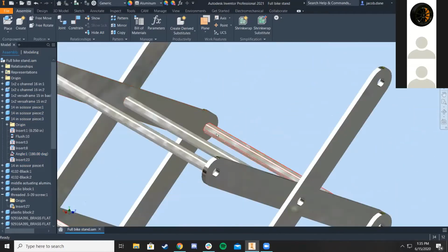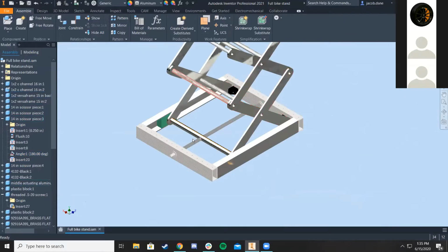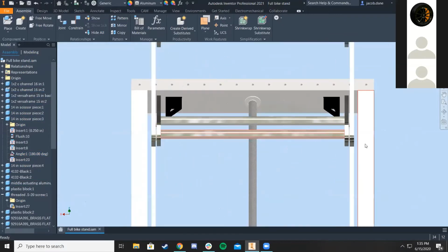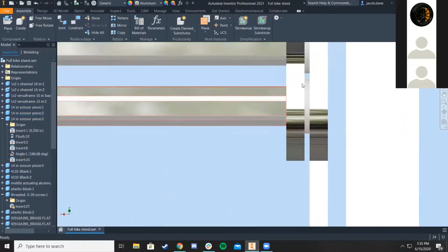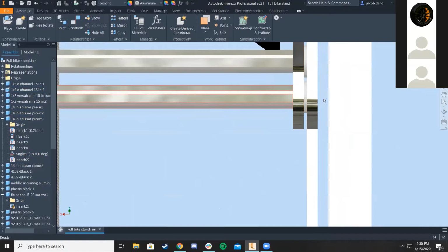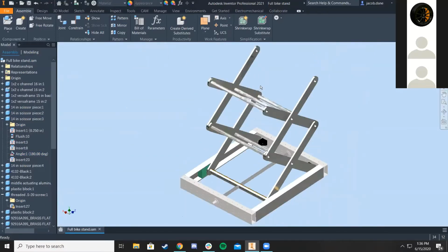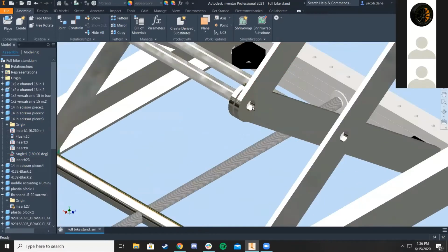And there's also washers. If you click on the back view, there's little tiny washers in there. Those are also in between. You probably just constrain it when you're constraining the scissor pieces, onto each of the edges, and it'll put it nicely. And the hole of the washer fits nicely with this hole here.